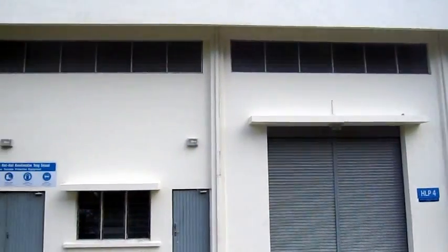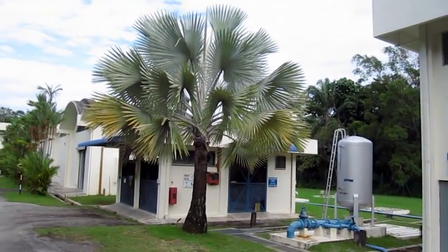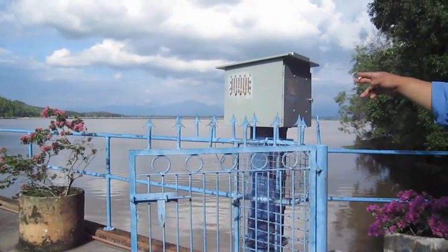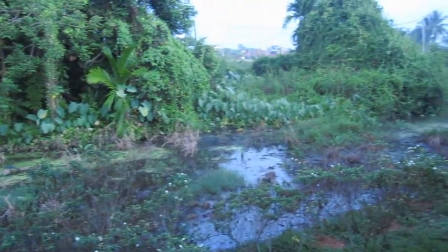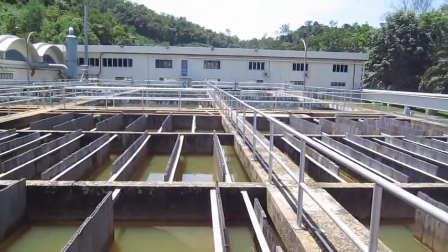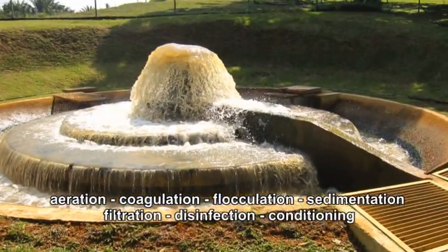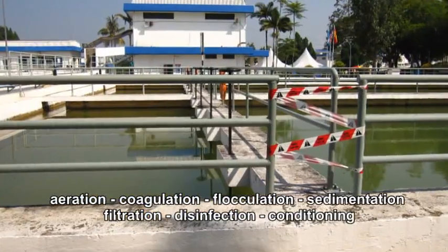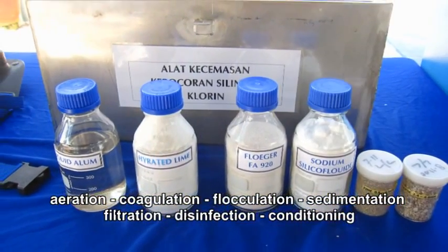Water supplied to consumers has actually been through a few processing and treatment stages before being distributed. Rain that falls into the dams or rivers flows to the water intake, where it will be pumped to the water treatment plant. Here, the raw water is treated by going through the process of aeration, coagulation, flocculation, sedimentation, filtration, disinfection and conditioning.